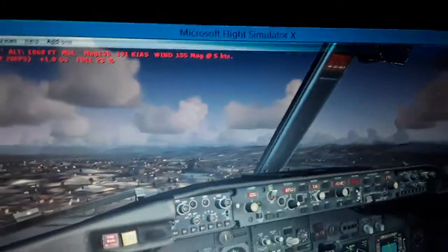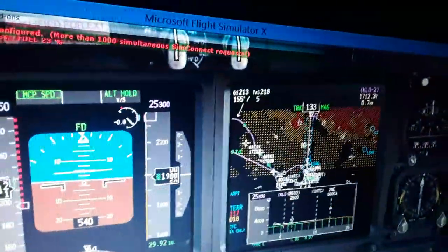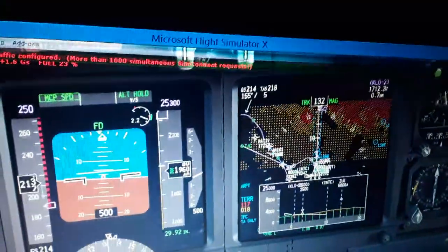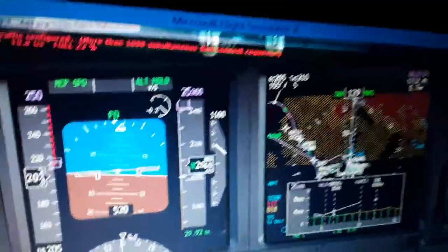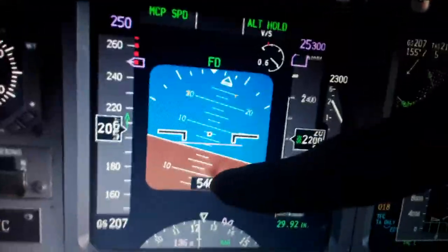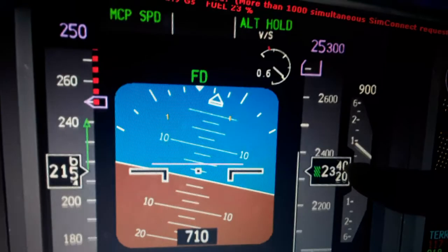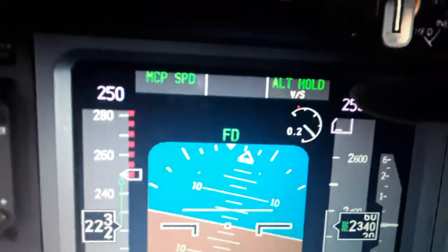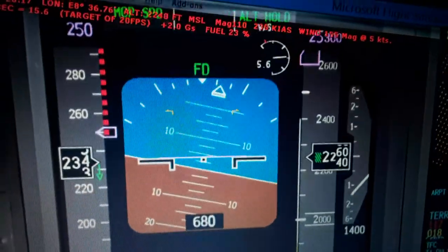And we have like 30 more minutes for this flight. So thank you very much for joining. So here we have the modes here. As we climb out, we are just 500 feet above the ground level right now. Keep climbing up. 1000 feet per minute, maybe we're going to increase that. You can see the radio altitude here, 500 feet above the ground level, but 2300 above the sea level. So we have the mode control panel, the altitude hold, the airspeed, the rate of climb.